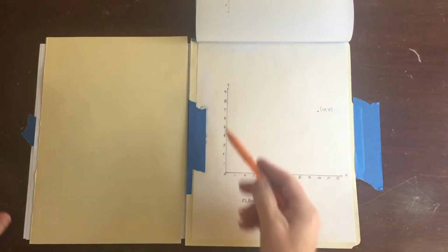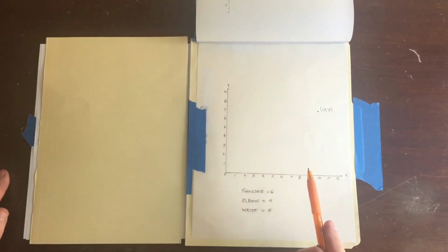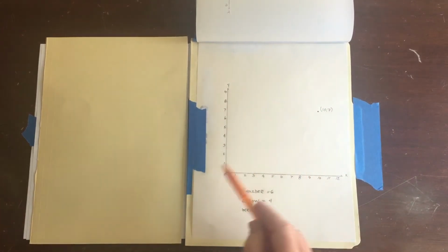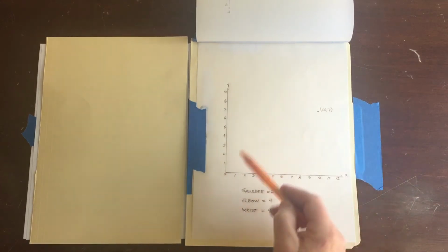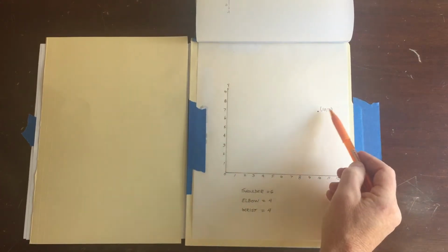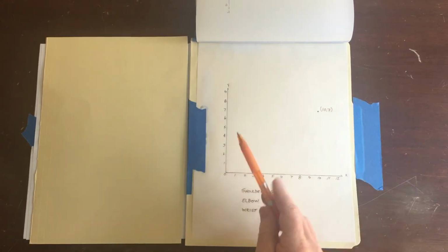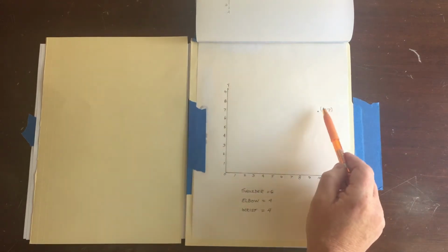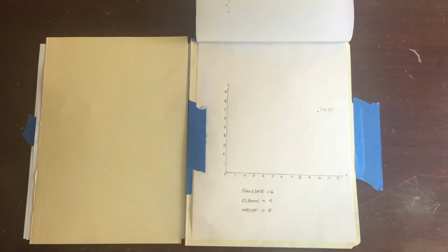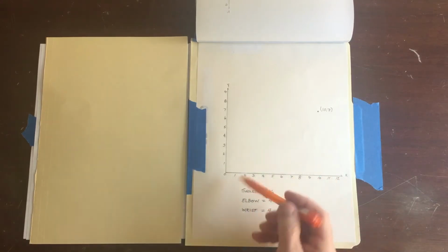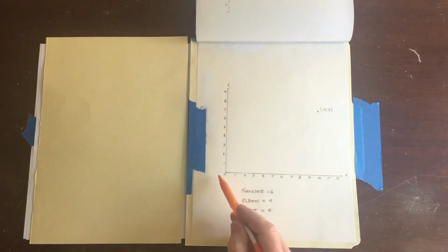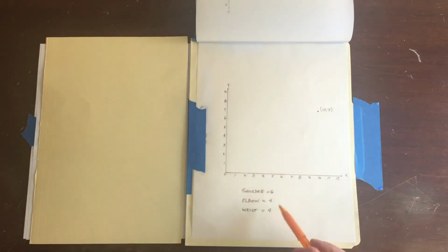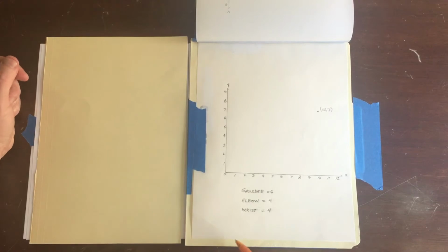So I want to try to solve this and explain the formulas necessary to find the inverse kinematics to get from this point and this point so that all the servos line up and meet right here at this point, 10, 7. We know that this is our x-axis, this is our y-axis, so we're over 10 and up 7. We know our shoulder, elbow, and wrist lengths in inches. So let's look at the first bit of information we need.